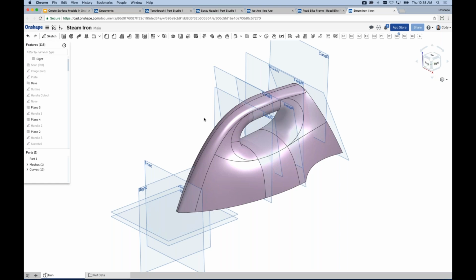Question, can I import a Modo surface model and create a solid? Well, that all depends on the format. I don't remember if Modo specifically is on the list. I don't think so, but I can double check at the end here, so bear with me. But if you can export to a format like Parasolid or Step or IGES or one of those formats and import, yes. So I can get into the list of translated formats in just a bit. I'm not certain we can import Modo native, but if they can translate, maybe. So forgive me, not 100% certain.